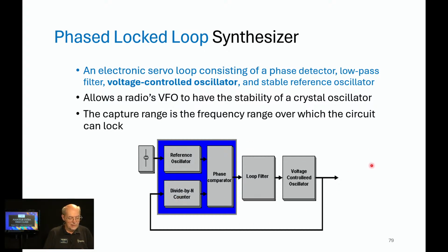The output of a phase lock loop is a sine wave. It's nothing jagged, it's nice and clean. The only difficulty with phase lock loops is they're always hunting. They're always going slightly above or below the frequency that you've set for them. This constant hunting causes an effect known as phase noise. So with that, let's see what we've got here.